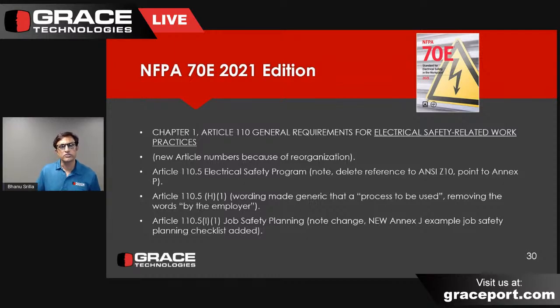And then they also included, instead of just conductive locations, wet locations. So portable cord and plug connected electric equipment used in conductive or wet work locations should also be approved for use in those locations. So the change is basically going from just conductive to wet locations. Okay. So that last one is equipment used.